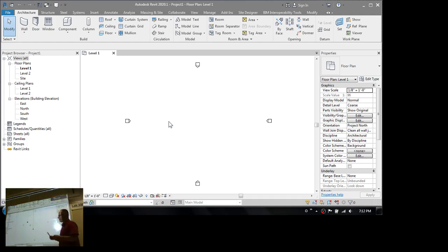Okay, so here's the Revit drawing area. If you have a building that has a second wing on it, a secondary wing, that's fine, but keep the major axis of the building, its long axis, aligned with the drawing area. You can either draw it horizontally or vertically, whichever suits, so that you have project north for the project pointing directly up on your screen.